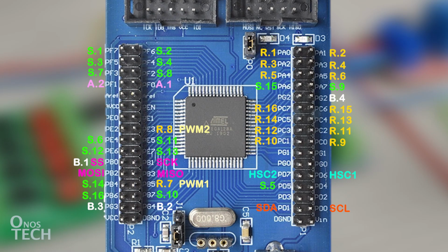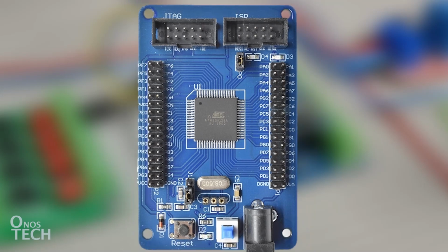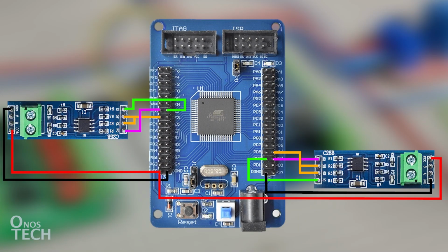The Modbus Master UART RX, TX, and D are mapped from PD2 to PD4, while the slave RX, TX, and D are from PE0 to PE2. For Modbus communication, this MAX485 TTL to RS485 module is connected to the master and slave UART pins as shown.